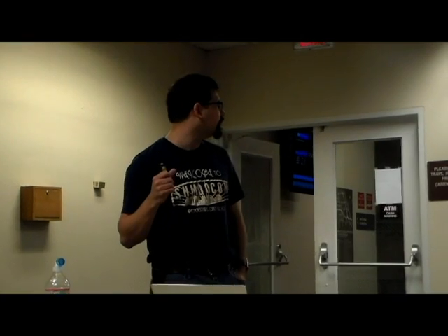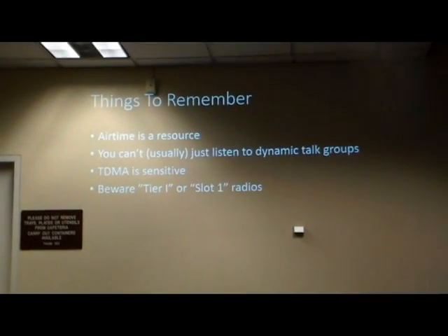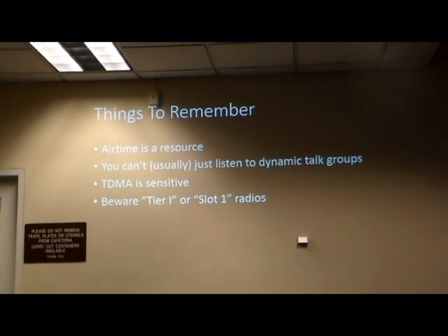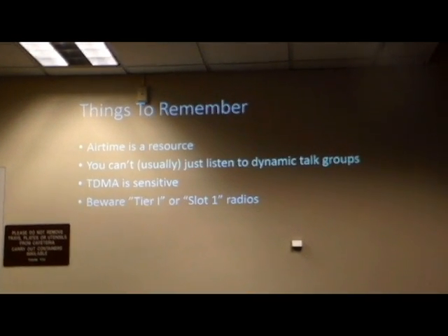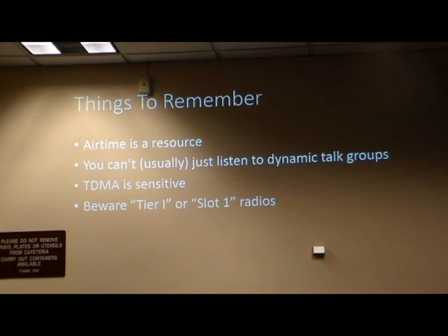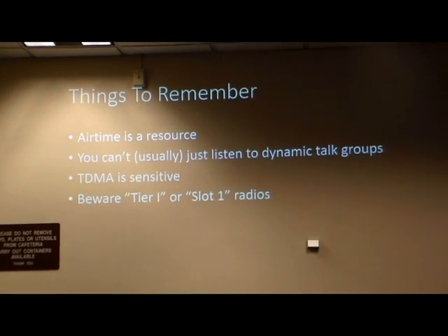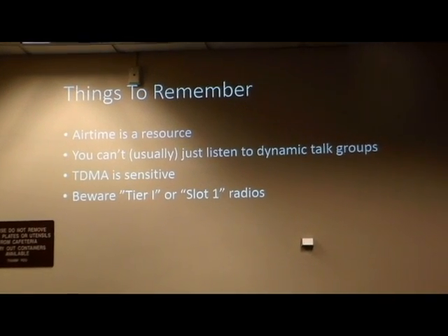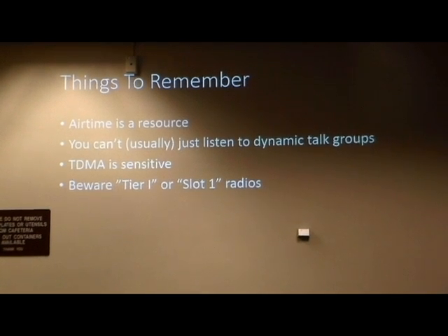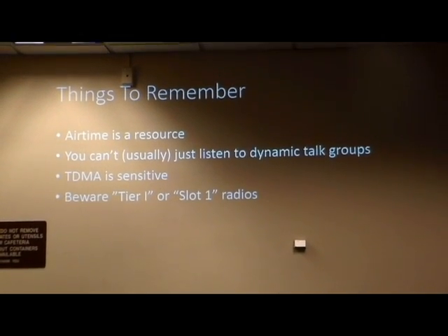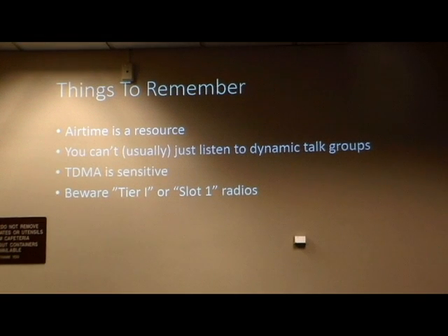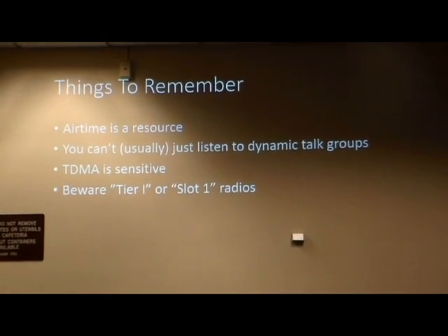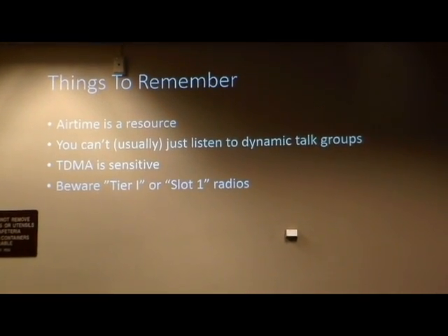And last one, beware Tier 1 or Slot 1 radios. This is really related to that TDMA being sensitive. There are a couple of manufacturers out there, Baofeng in particular, that have tried to get into DMR and produce what they call Slot 1 radios. These are radios that have a couple of flaws where they cannot do that timing quite well, and when you transmit on them, they just wipe out both time slots.